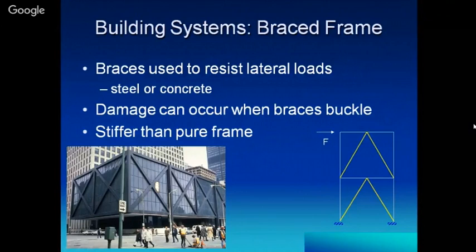If it has viscous dampers or fluid viscous dampers in between these cross bracings, then in time of an earthquake the bracing part will be damaged and will work like an electrical fuse, letting itself get damaged and safeguarding the building, not letting the structural elements of the building be damaged.